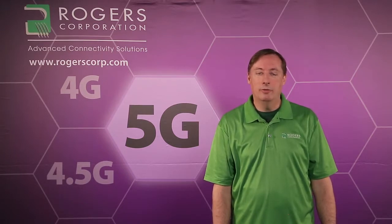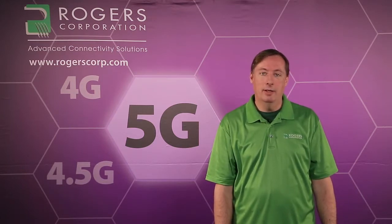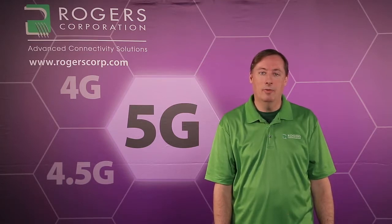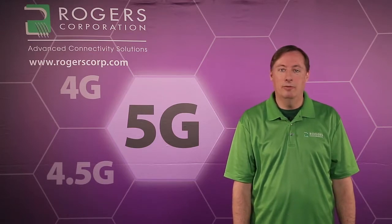There are different ways to characterize moisture absorption of the raw material or the circuit. More commonly, lately anyway, is a test called 85-85, which is conditioning the material or the circuits in an environment that's 85 degrees C and 85% relative humidity for some period of time. Then you test the material or the circuits before and after this and see how they respond.